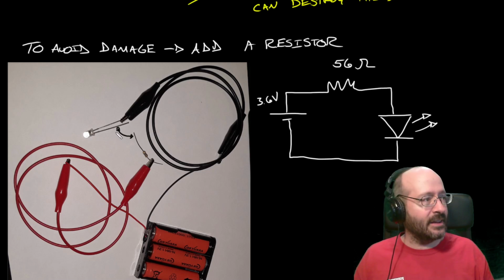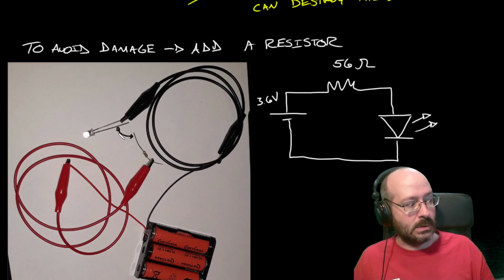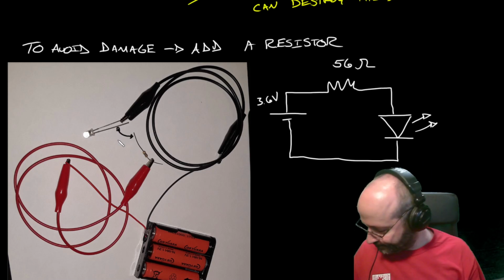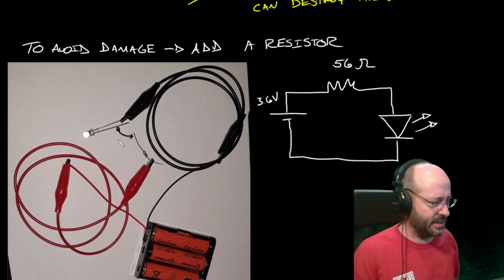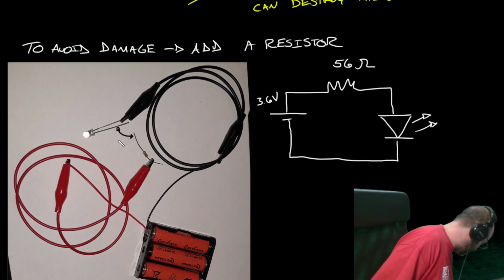So take another alligator clip. Flicker, flicker. Uh-oh. Are you making good contact between the probe, or between the resistor and the anode? Okay. Twist them together. Make sure all your connections are good. If it's flickering, that's usually not a good sign.